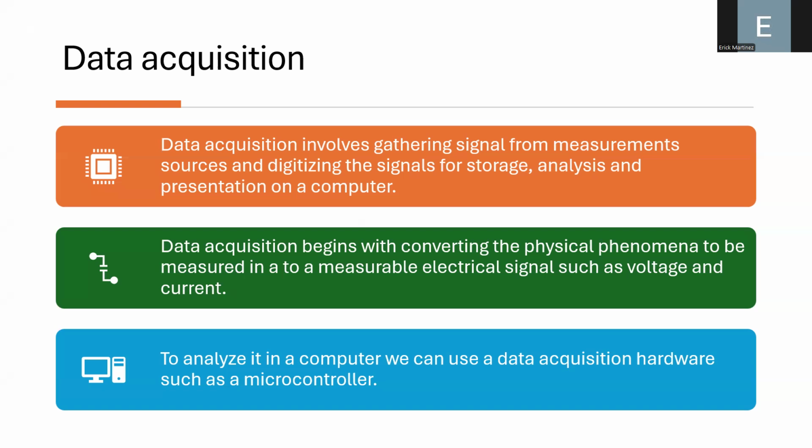Okay, this is only an overview of some of the sensors that you can see, but I want to concentrate on another aspect that is typically overlooked. You can have the sensor, but sometimes some people miss that you also need to be careful about how you are pre-processing the signal before sending that information to a computer or to a data acquisition system, for example. You maybe need to use a microcontroller like an Arduino to collect the data, but the microcontroller needs the electrical signal in a particular format or presentation.